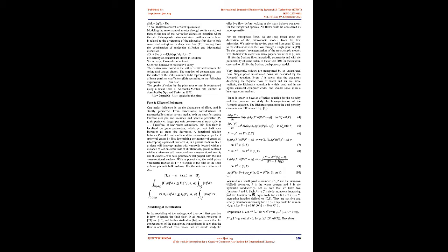Modeling studies. The mathematical models consist of integrated hydrological and solute transport models and are used to simulate contaminant movement and subsequent uptake by plants. The hydrological model is based on Richards's equation for the transport of water through soil in response to the forces of gravity and water pressure.